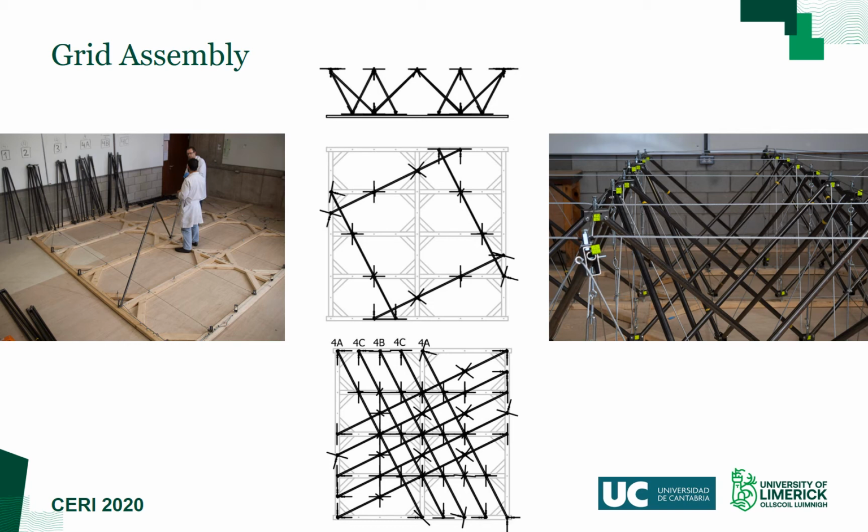The diagonal cables are then placed and the grid completed by the addition of the vertical tensors and the closing of the inner node fixing plates. The vertical tensors seen here are the active elements of the structure. Through shortening of their length using a turnbuckle, the grid is forced to expand a bit like a scissors framework, and a state of self-stress is introduced into the grid. It was determined that a shortening of the tensors by 50 mm would achieve the targeted self-stress and provide a stable and rigid grid, which could then be lifted into position.